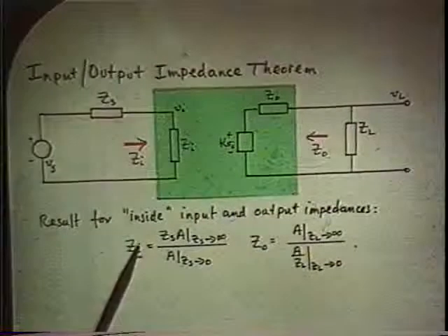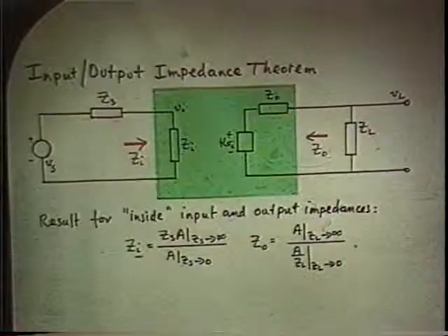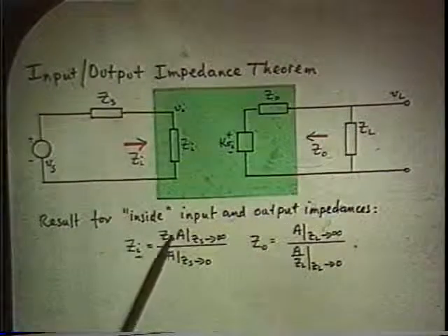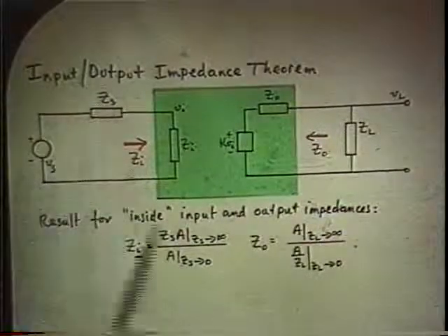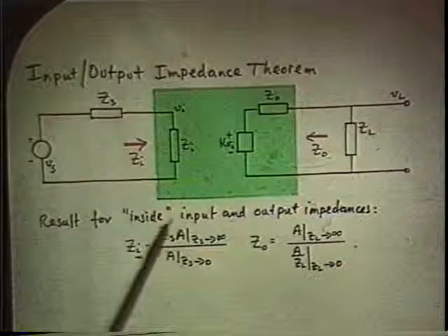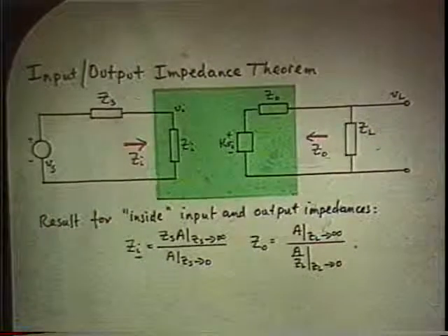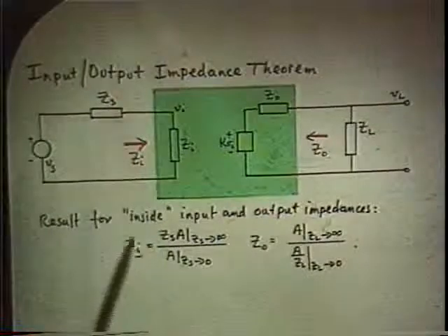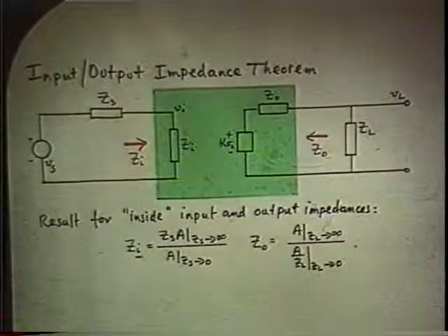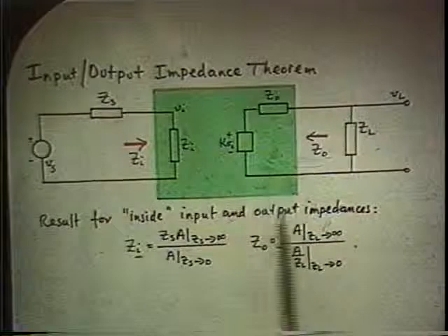And exactly the same thing applies to the input impedance. Again, you use the answer for A that you have already, which contains the ZS, and you take those two simple limits with respect to ZS, and in a line or two of algebra, you have automatically in factored pole zero form the input impedance. Huge saving of work.